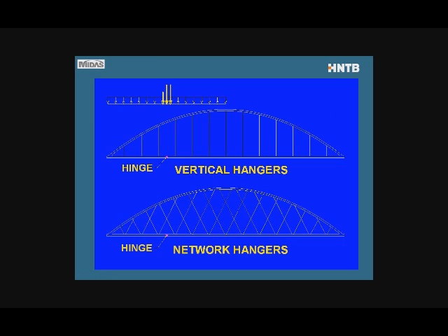And I will compare these 2 systems under this loading combination that's indicated in the upper left corner. So this represents live load over half the span, so there's some lane load and some truck load. And the crucial part of this is that it's only a partial load, which structural engineers among you know, arches are very, very efficient under uniform load, but they kind of fall apart under partial live load and pick up large bending moments.